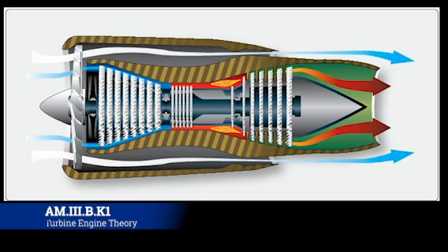If you look at this cutaway diagram of this turbofan engine, imagine you're the air coming in. For right now we want to pay attention to the blue lines on the left-hand side, on either side of the spinner. That air is going to come in to that first set of turbines, and what's going to happen is it's going to start to be compressed.